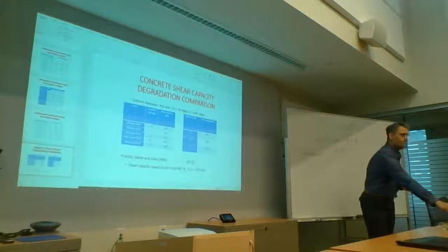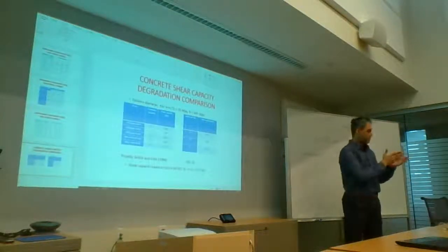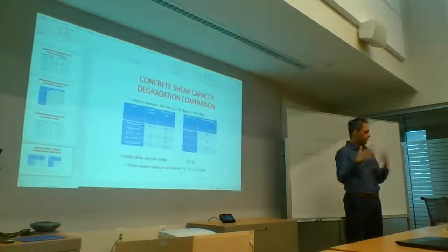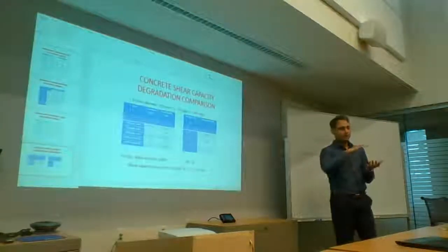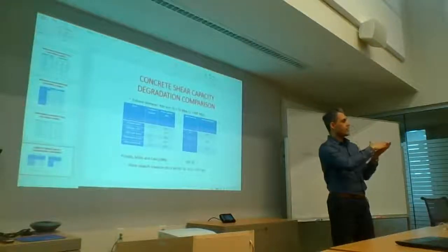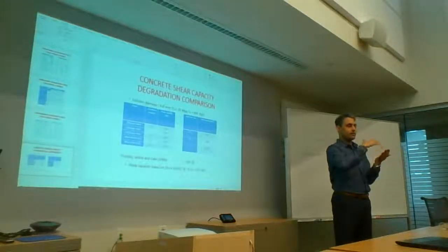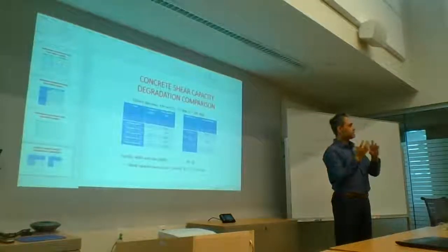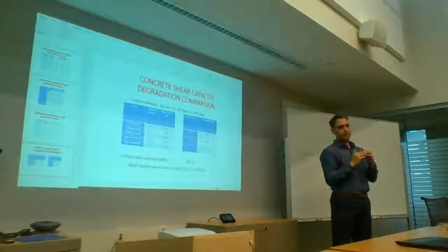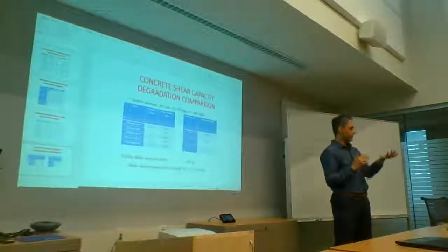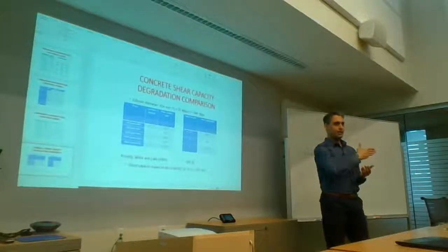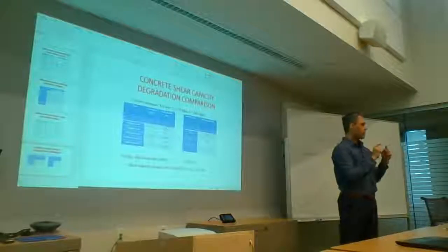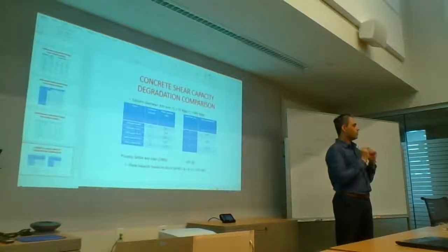I always like to give a comparison here. I think that's a good question. If you think about the seismicity of the Lower Mainland, Metro Vancouver, the difference between the 475 response spectrum and the 2475 response spectrum is anywhere from 70% to 100%. So your demand is going to increase by 1.7 to 2 times. Now you look at the capacity side of things, and according to the code, for 475, your rebar strain has to be below yielding, which is 0.002.